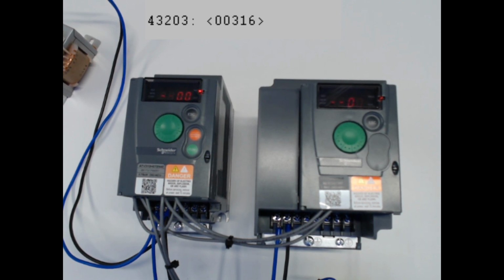But in the end, you know what I did? I just told him, oh, forget about it. Just sell me a step down transformer instead, 415 stepped down to 220. Then he happily sold me the transformer. So basically, a transformer is a transformer, a coil is a coil. If you put in 220 as a supply and 415 as your load, as long as your load is within the kVA rating of the transformer, it is fine.